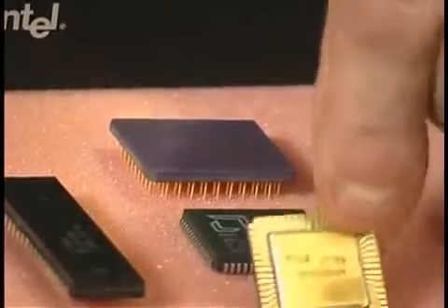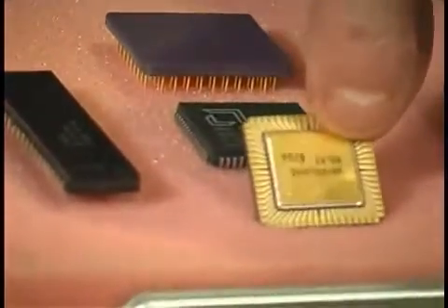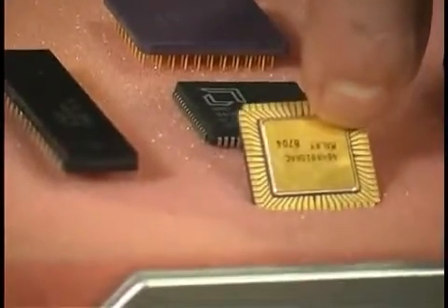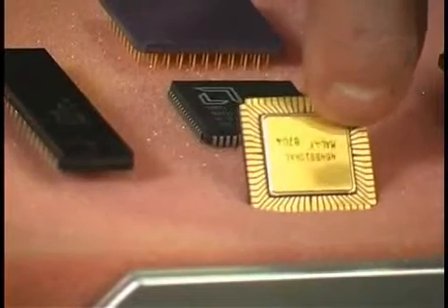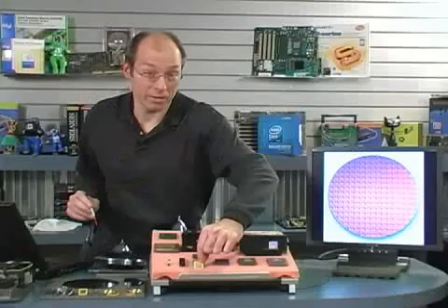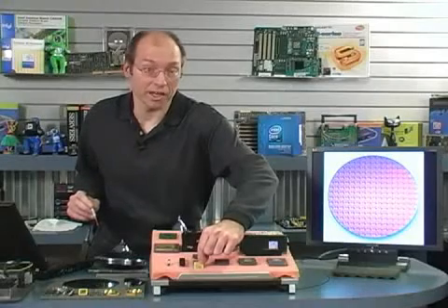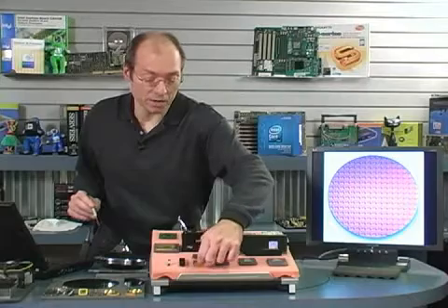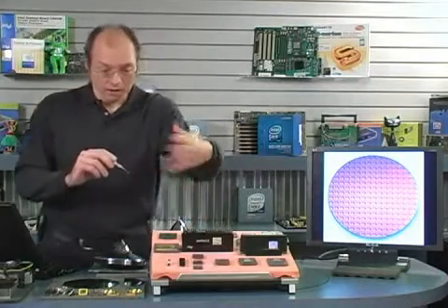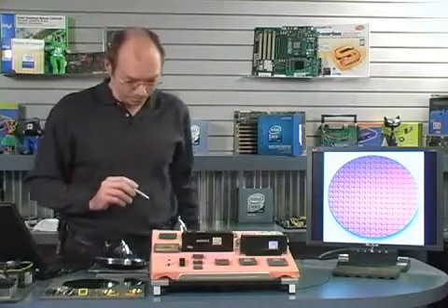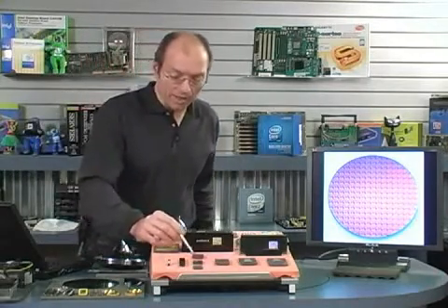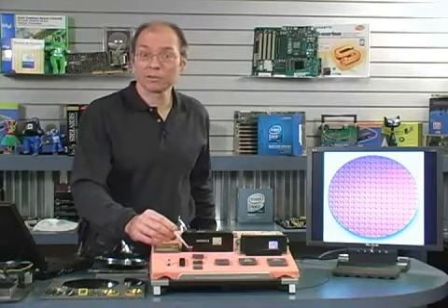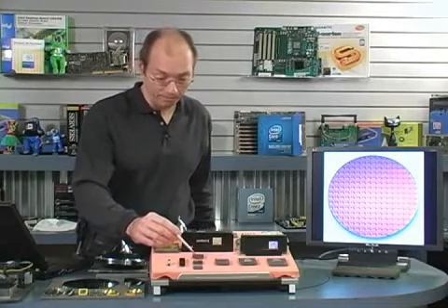And then this one had no pins. The pins were actually in the socket on the motherboard, and there were just lands around the chip. Now what's interesting is that just in the last few years, this type of packaging has returned, and most of Intel's processors now use this land grid array, they call it. So at this point, processing speeds went up to about 10 to 20 megahertz.